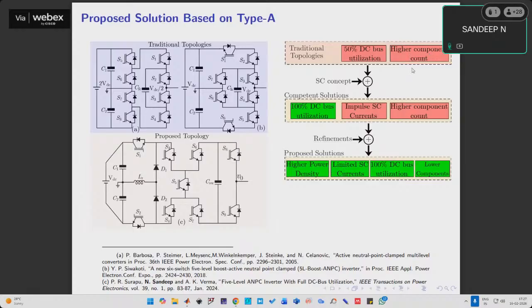In order to do that, we have to go for more and more switchings, more states, possible with more and more devices. That is how the complexity of a multi-level inverter increases. This complexity can be reduced by reduced component count multi-level inverters, where we optimize the structure so that with fewer components we can generate a multi-level waveform. That is the main objective.